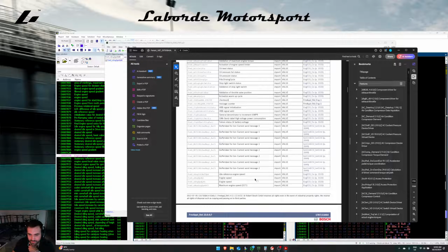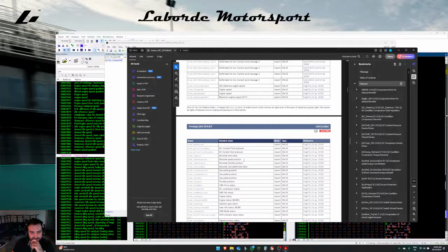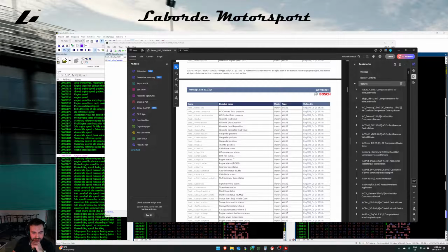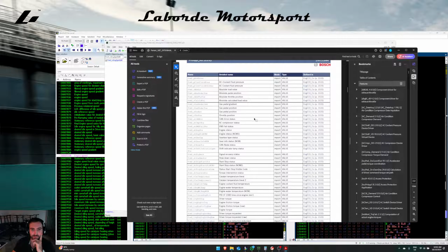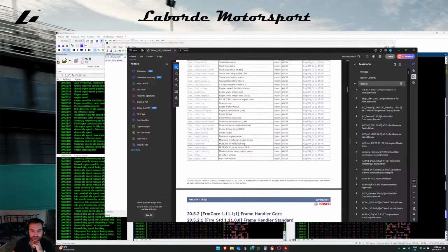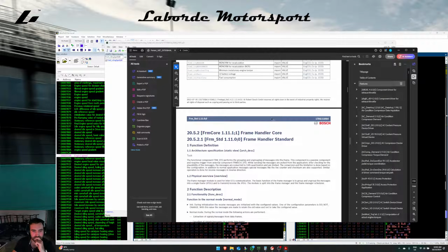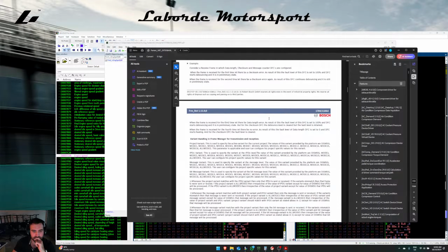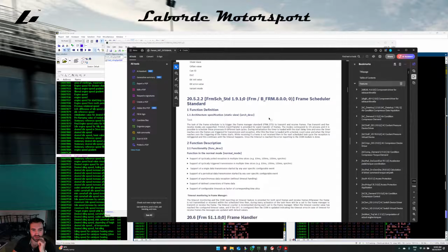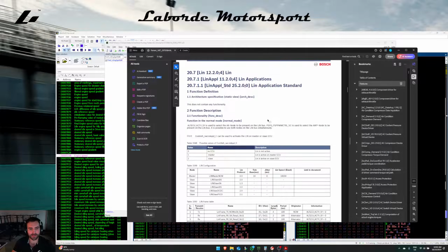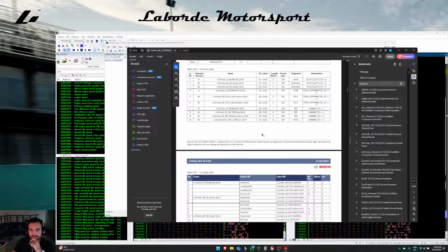Engine speed, yeah, we've got the 2 variables here that we still weren't able to find. So we're going to try and find them. Engine status, gearbox type, status, all this stuff. There's so much information that's sent over the CAN bus, right? So interesting. So if I can find the CAN structure of the file on the right hand side, I should be able to find it in the left.